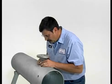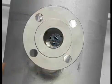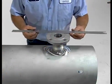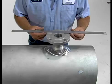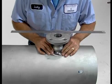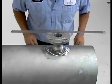Next, carefully align the mounting hardware so it is properly centered over the hole and not offset. Next, set a straight edge on top of the hardware and turn it until the straight edge is parallel to the edge of the pipe. This step is not necessary with the pack lock mounting hardware.